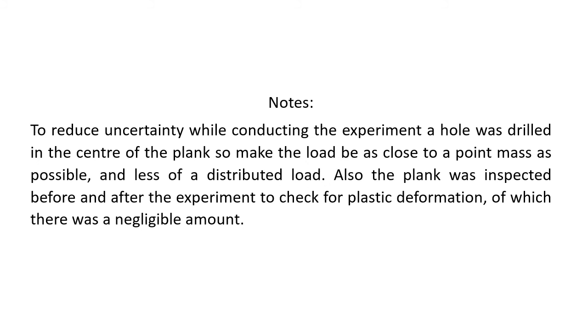And here are some closing notes from our experiment. To reduce uncertainty while conducting the experiment, a hole was drilled in the center of the plank to make the load be as close to a point mass as possible, because that's what the theory we used required, and so it would be less of a distributed load, although in reality it would slightly be that, being one of our sources of uncertainty. Also, the plank was inspected before and after the experiment to check for plastic deformation, of which there was a negligible amount, which was good to see. I expected some plastic deformation, but luckily there wasn't any.